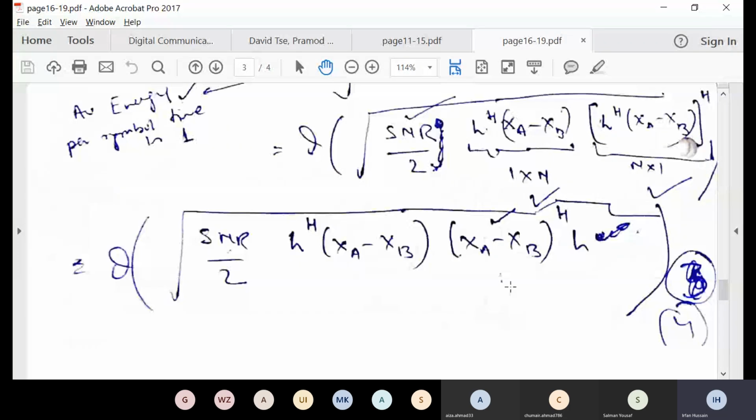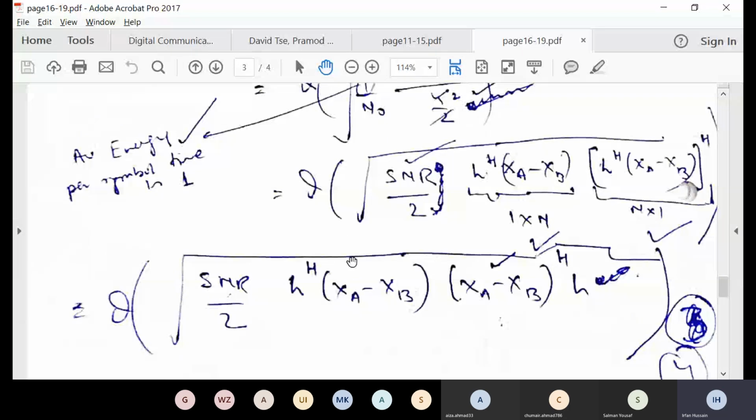So I think we have derived up to this part here, the SNR. The book uses H conjugate, but it is better that we use HH, because H-Hermitian means transpose plus conjugation. If you compare this with the book, you can see everything has been derived. Now here is a very important result: this complete matrix is actually Hermitian.